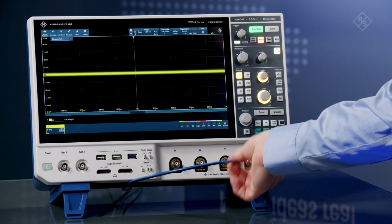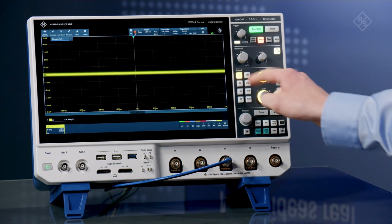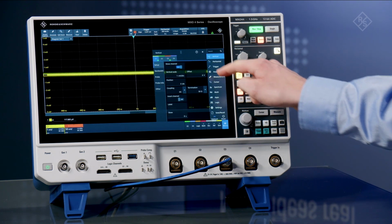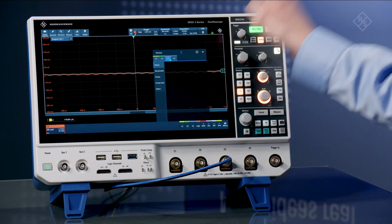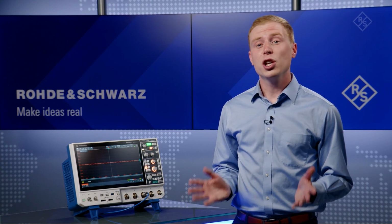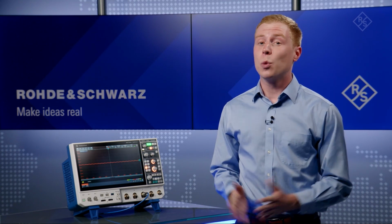Here, I'm going to plug a pulse into channel 3. I'm going to turn on channel 3 and then disable channel 1. Signal peak-to-peak power integrity measurements are often in the millivolt range. Using a scope with more noise can falsely show your power rails are out of spec, when in reality they are within required tolerance levels.